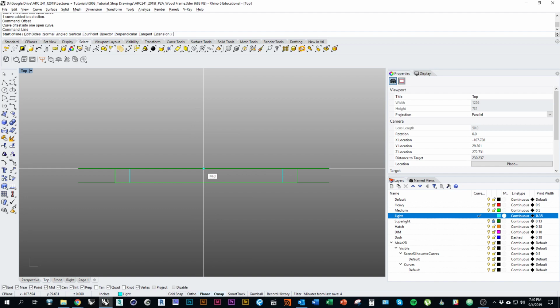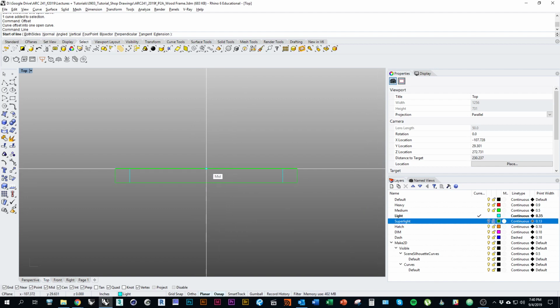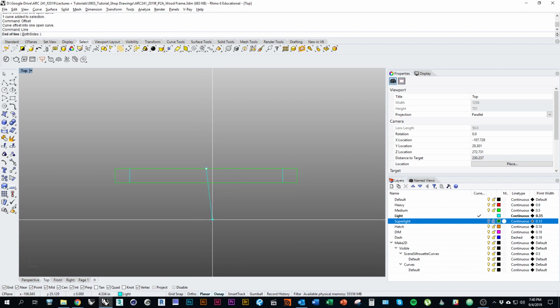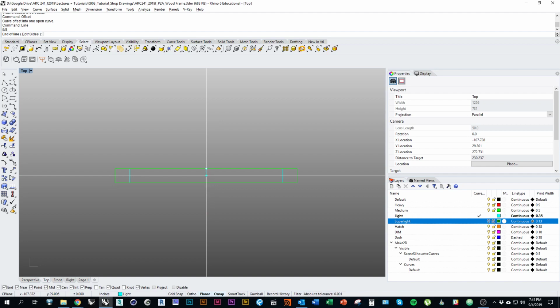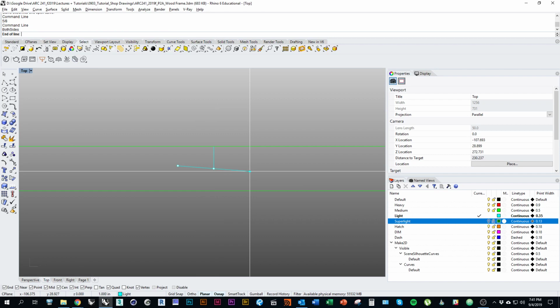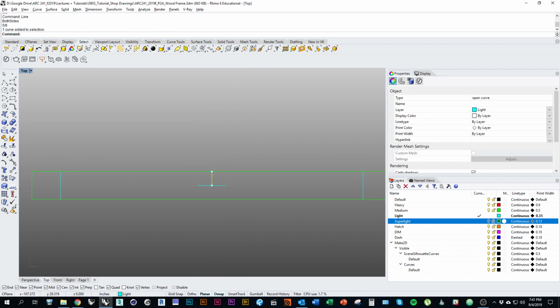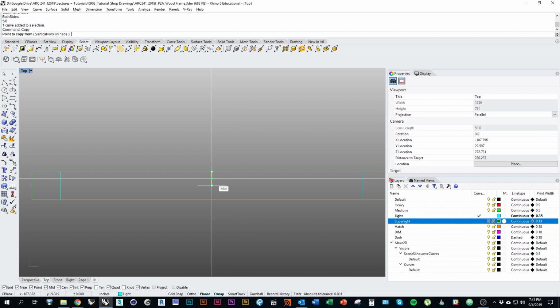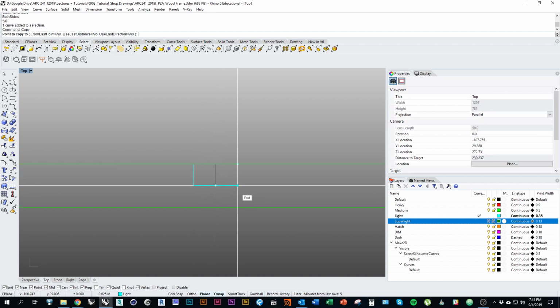And there's probably two midpoints here because we have, I'll just turn my construction line off. I'll draw a line straight down from my midpoint. Again, half of 1 1/4 is 5/8. Okay. Then I could type in line, choose the option both sides. Again, 5/8, hold shift. Okay. And then I could just copy this to either side.